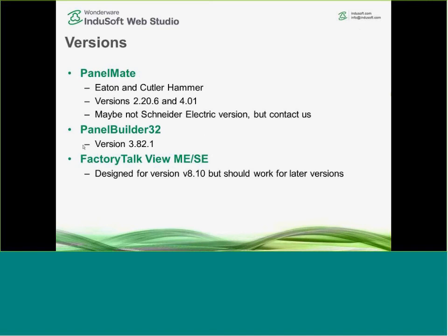For PanelBuilder32, I've been told version 3.82.1. Now, again, it may not be limited to just this version, but it's at least these versions and later. But later versions are not always 100% supported either. FactoryTalk View ME and SE: this was designed for version 8.10, but it should work for later versions as well. And as always, conversion utilities and import tools are not 100%. They never will be. They often can't be. But we've come very close on a lot of these.